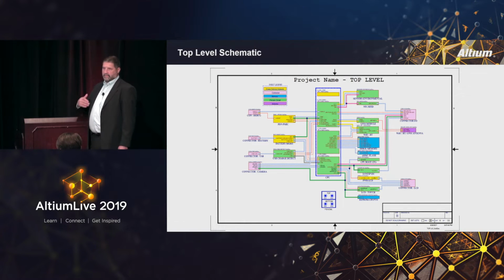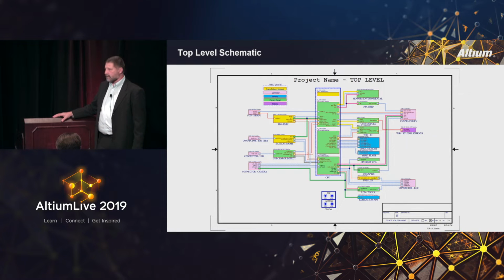And in my experience, that's where most rework is, right at that connector. And if they've pushed all the parts right next to the connector, it's one of the most painful too, because now you have to move everything to make room for the ESD components that need to be near that connector.